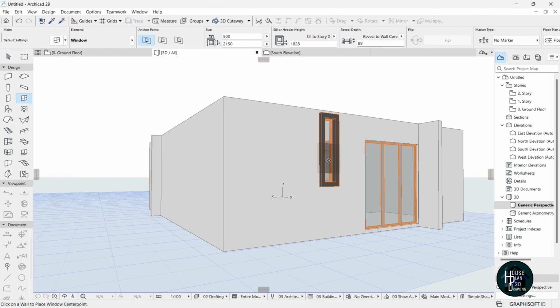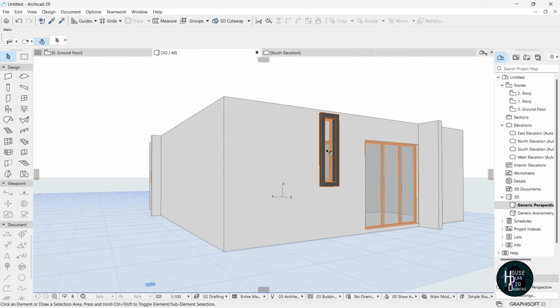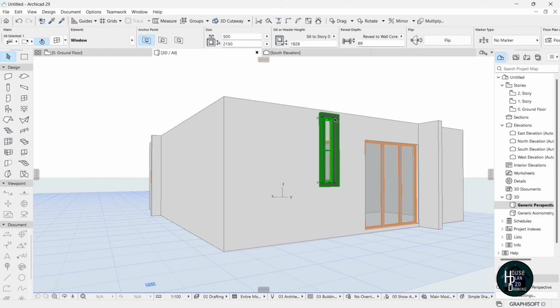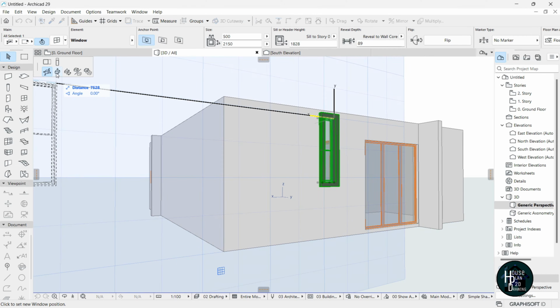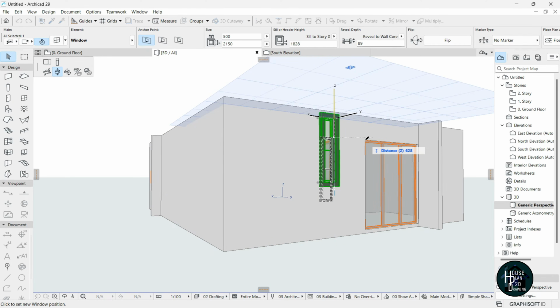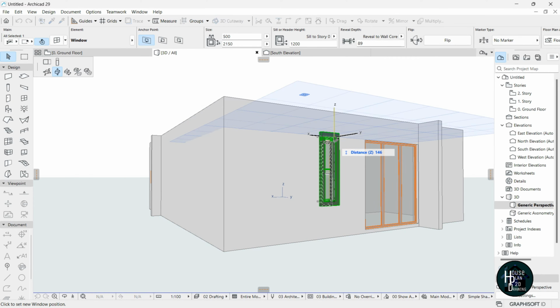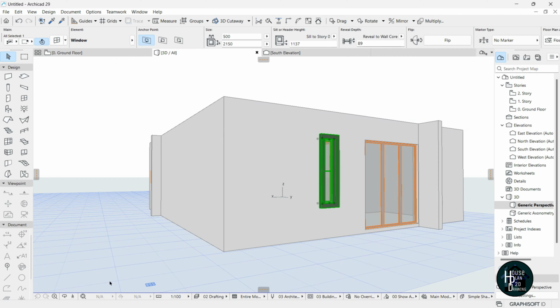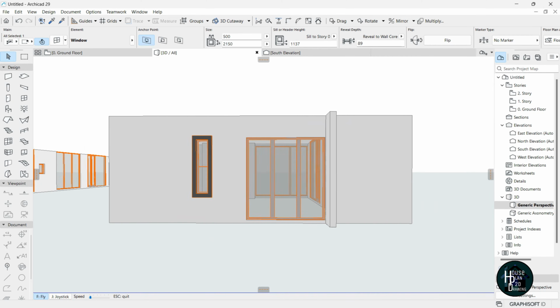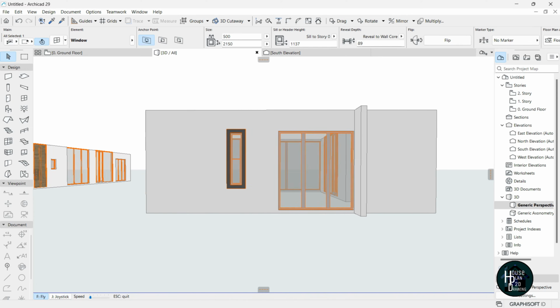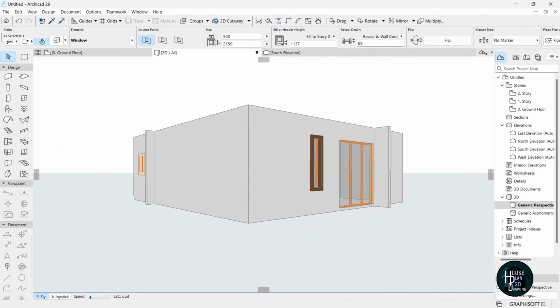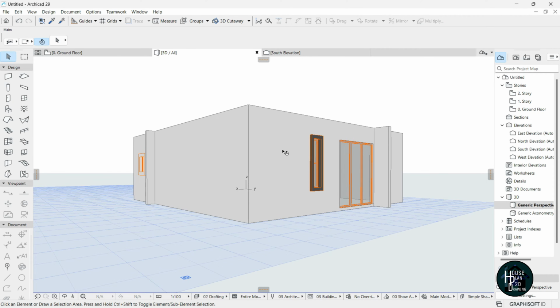As you can see, this is flying up, so we want to try and bring this down. You can decide to click on the node there, select this elevate and pick that window there. Okay, you can also decide to click this and adjust it a little bit downwards, and for proper alignment you want to go ahead to elevations to work on that. Okay, so I'm going to be fixing the toilet window here also.